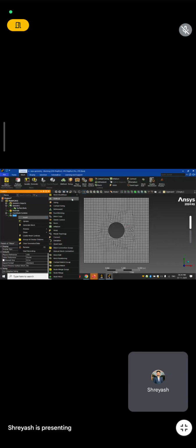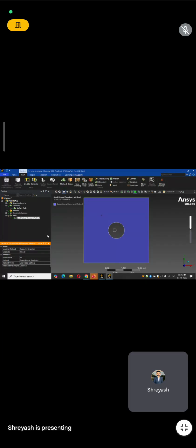Okay. So let us go to the method. There is an option called automatic method. यहाँ पे हमको geometry select करना है. Apply. So here you can see there are different methods for meshing. There is quadrilateral dominant. So basically all the quadrilaterals, all the squares, okay, with four sides. Okay, then there is option for triangles. There is option for prime mesh. Okay, there is option for multi-zone.